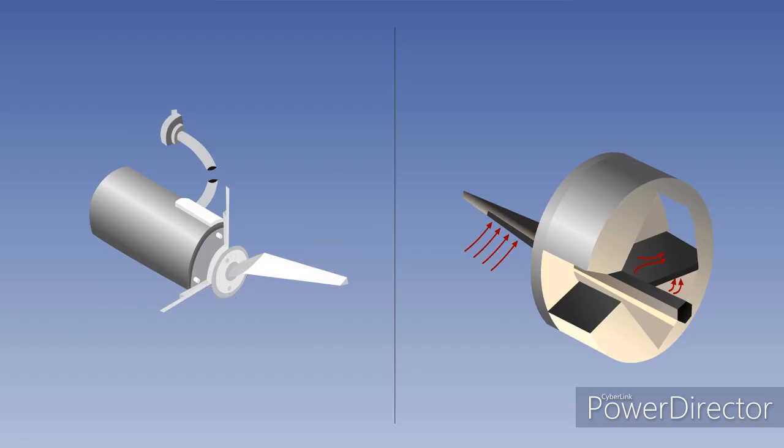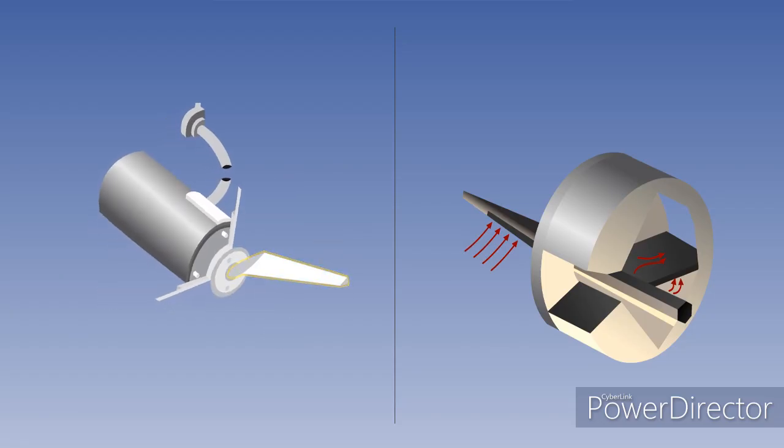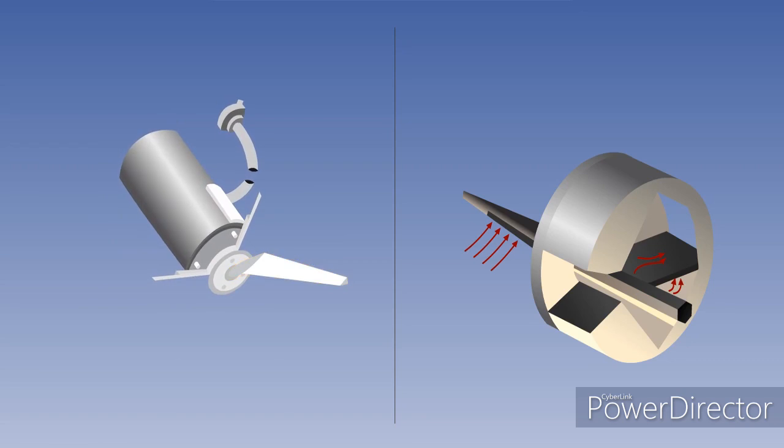The vane detector is a counterbalanced aerodynamic vane, which positions the rotor of a synchro, which is used to measure the subsequent angle. The conical probe protrudes from the side of the aircraft into the airflow. The probe is attached to a paddle wheel inside the transmitter housing and has two vents set into it, which feed either side of the paddle wheel.